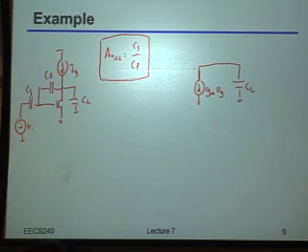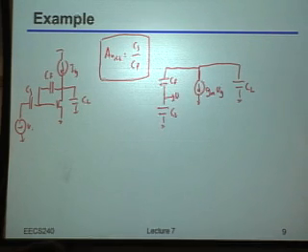And then to model the feedback network, I'm just going to, again, draw those two capacitors over here. There's going to be a CF there and a CS here, and then this is going to be VG. I obviously tweaked what was horizontal and what was vertical a little bit, but trust me, this is indeed an exactly identical small signal circuit. Of course, now the next thing I have to do is add in the noise current due to that GM device.